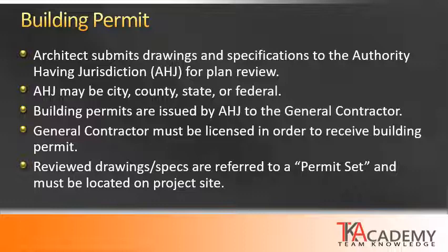The reviewed drawings and specifications through the plan review that are approved by the authority having jurisdiction, this is called the permit set. This is important: the permit set must always be located on the project site.